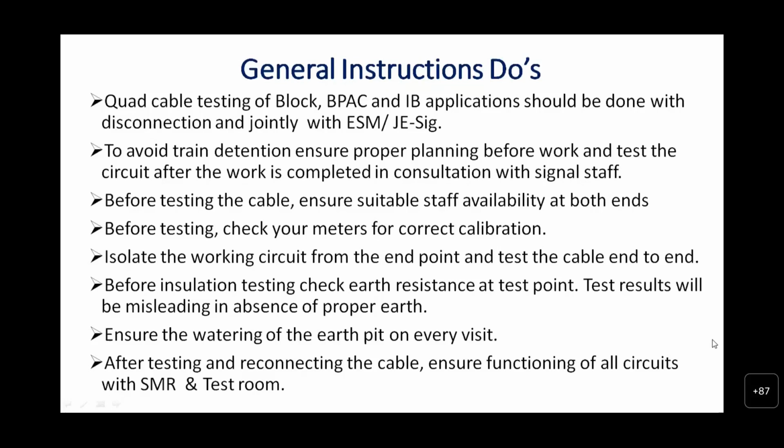Before testing the cable, ensure suitable staff are available on both ends of the stations. Before testing, check your meters for correct calibration. Isolate the working circuits from the end point and test the cable end to end.